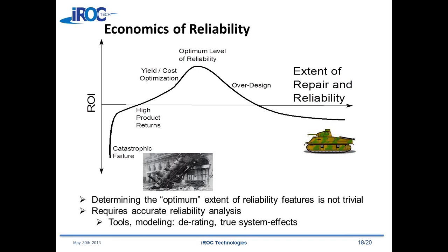So as that rate gets higher, the costs increase. And then at some point, if you're really sloppy in your design, if you're designing without ECC on your memories and you're not worrying about your packaging materials, you get into an area where you're going to have a catastrophic failure, a product recall scenario, and that's where you really don't want to be, because the costs can go through the roof and could really ruin you.